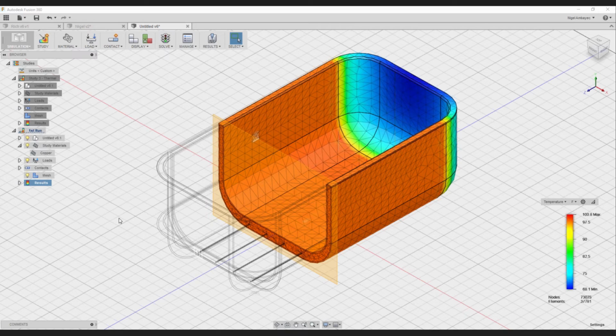So it could be too high. That's kind of why when I'm running all of these sims, you need to look up the material properties and everything. You need to make sure you do your homework in regards to constants and emissivity values and everything else in regards to radiation, because if you do put the values in wrong, you could get crazy results like this. This is expected because I made it this way on purpose. So the other thing to mention when you're doing simulation is to give yourself a sanity check.